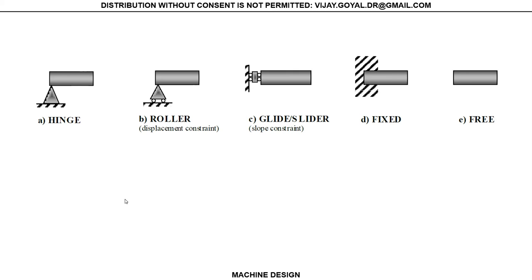So the other thing that you have a lot is different types of boundary conditions. How do we manage these? Well, here what you know is in a problem like this, you will have a reaction in X, you'll have a reaction in Y. It's called a hinge or a pinned boundary condition. I'm sorry, I mixed these. This is reaction in X, reaction in Y, if I use the coordinate system where this is X and this is Y. Here, I only have a reaction in Y. It's free to move horizontally.